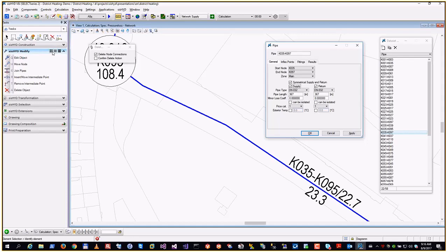Some people maintain this information. Others use statistical data. So if this is a straight pipe, we know all pipes have a certain amount of bends. So we do not compute with the pressure loss of the straight pipe, but we increase it by 10 or 15%. And this accounts for the mounting parts and for all these bends inside.